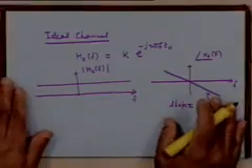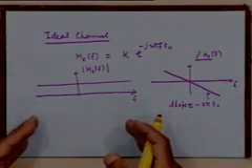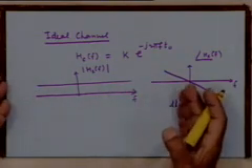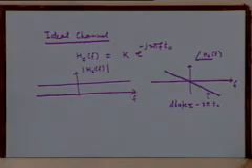Of course this kind of ideal channel is too much to expect to be available in practice. It's not even required if you really look upon it, because in real terms you will be transmitting a signal of some finite bandwidth, not of infinite bandwidth. So our concept of an ideal channel can be made less stringent. As long as these characteristics hold within the bandwidth of the signal, we should be quite happy, because what happens outside is of only academic interest, since the signal does not have any frequency components beyond some value.